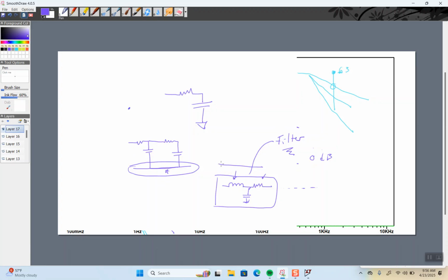And what Joe's talking about is that for high frequencies, it might not be ground. If I have a low pass filter, high frequencies are going to be attenuated and it won't bring it down to ground the way you want, right?